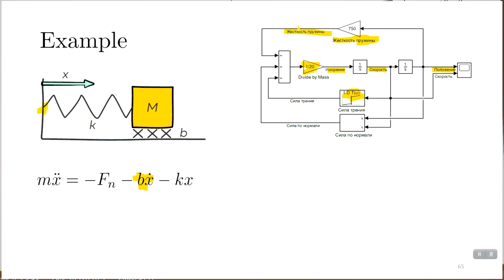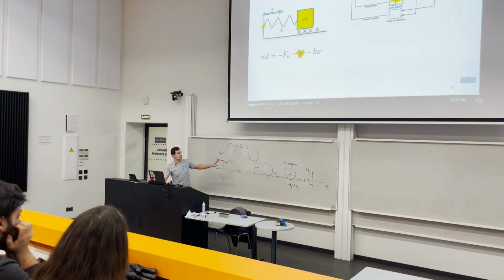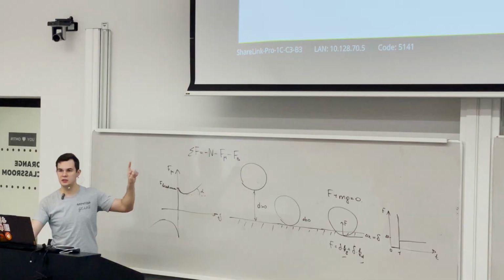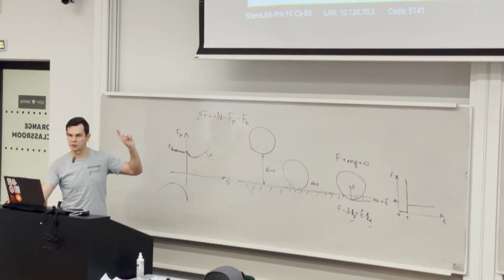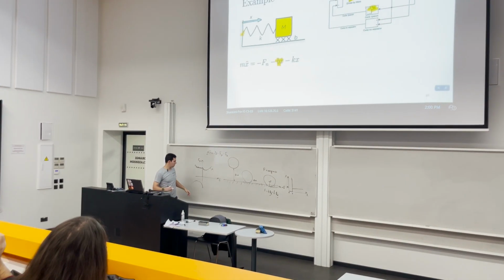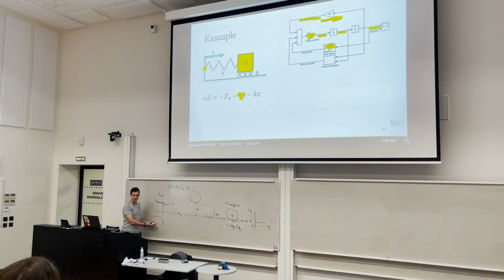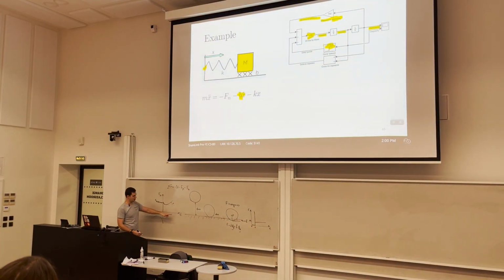All right. Then, right here, we can use the equation that I just showed you in Simulink. But in this particular example, I used an even simpler model. I have used a lookup table here. It means that if we already have a plot like this, we can feed it with the velocity, and it gives us the force as an output. And right here, this block computes the friction force.